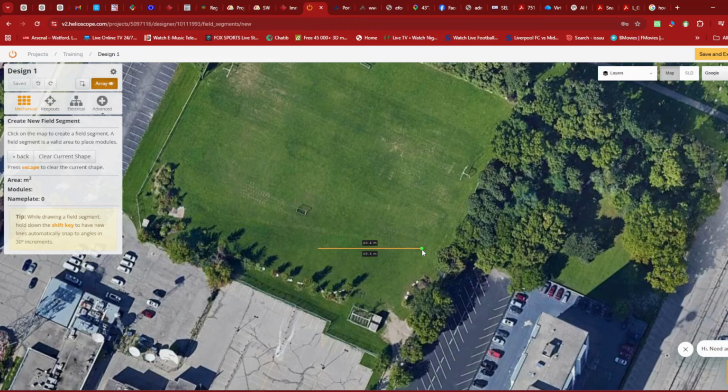Because don't forget that the sun rises from the east, right, and sets in west, but it will move towards south. Right? If you are in South Africa, I think it goes the other way, so it moves towards their north. So your panels need to face the northern side, right, north side, for it to be optimized.